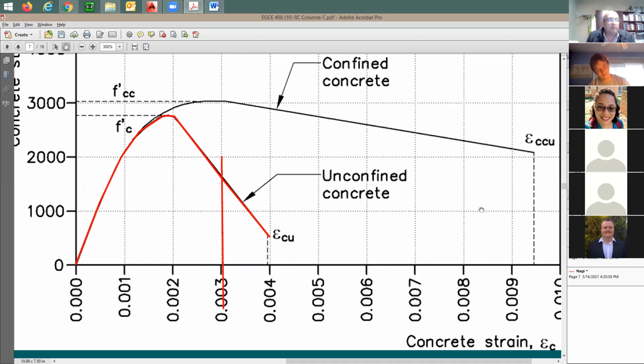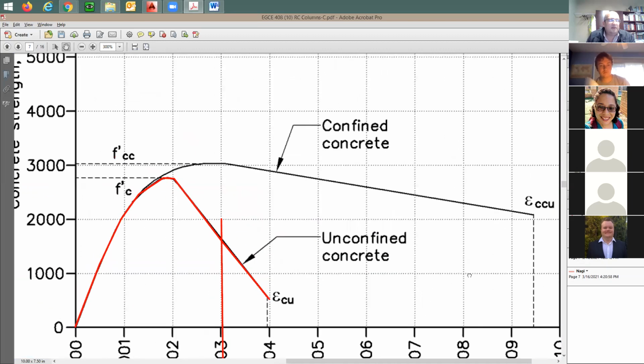In reality, when you apply this amount of confinement, the strength of the concrete itself gets larger. I mean, it's going to be much higher, maybe about 15%. See what happened here in terms of the performance of the concrete? Right at this point, the confined concrete property starts to go up. You see this here, F prime CC? F prime C is for concrete, CC for confined concrete. And it says here confined concrete. You see the trend is going higher, maybe 10 to 15% at least.